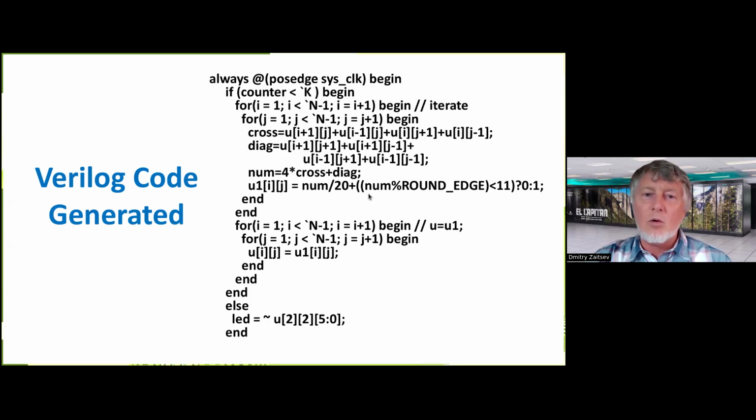Here in this Verilog code, I would like to attract your attention to this round H parameter. Because we are using finite difference approximation, when we receive some remainder, we need either to add 0 or add 1 depending on the value of this remainder. It is a parameter that is sometimes good to adjust for convergence, because for cellular automata it can either come to a certain value, because we have 1 at the smallest value after we apply scaling to obtain the integer value approximation, or we can obtain some pulsing configuration, some loop with low change of values, and it also maybe satisfies the criteria for convergence.